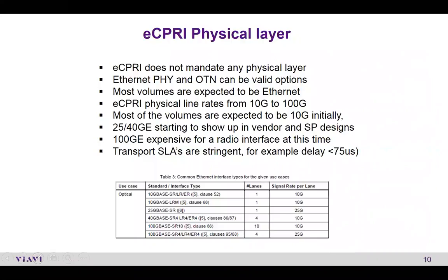So this is happening now. 40 gig is also available in data centers and also as LR4. Of course, one has to look into that. 40 gig is a QSFP already, but many things that I see in the field may actually use a QSFP with CPRI rate 8, basically 4 wavelengths, each carrying a CPRI rate 8 signal.